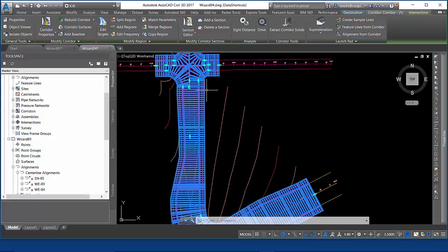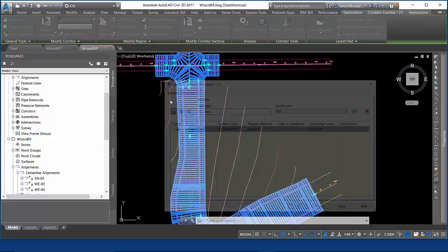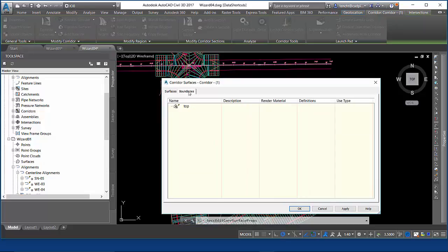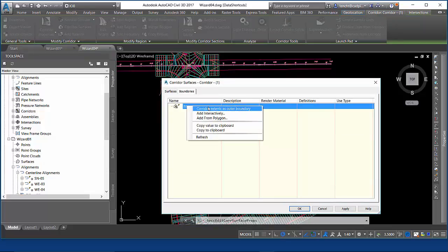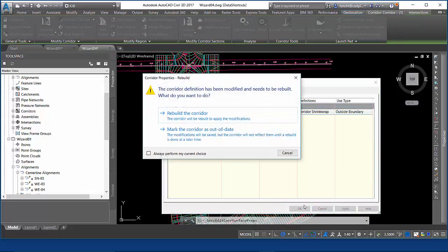If you have multiple corridors being added, you want to make sure you're getting surfaces that appear in both sets. So it was a good test before you add the boundary. And now we can just use the corridor extents as a boundary.